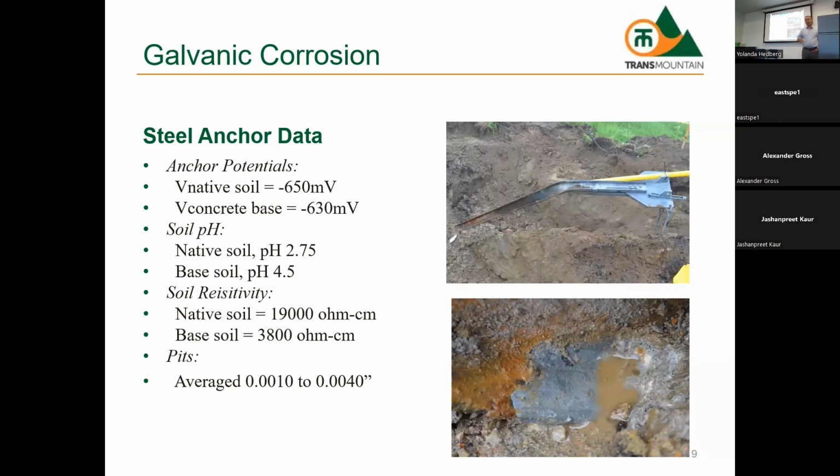So when I first got to this site, I was like, well, obviously it's corrosion. Obviously a guy wire broke because of the corrosion. Why did it break? I got to it, I'm like, well, it's galvanized, it shouldn't be corroding. There's something else going on here. I'm looking in the hole, and what do I see? Copper. What color do you think the copper was? It was red. It was beautifully red. It was so pristine.